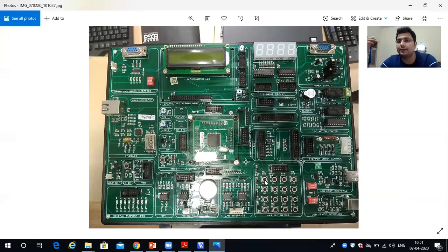Then after writing that program, we will compile and link those programs, and then convert them into a hex file. That hex file is later loaded through this serial interface. All that we will do in our system using Keil software, Keil MicroVision software. We will write our code there, and after compiling and linking, we will create the hex file. That hex file, using other software, we will load to the ROM in our core.